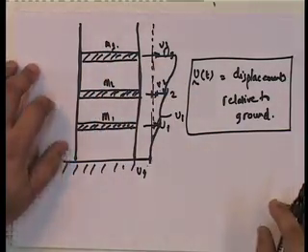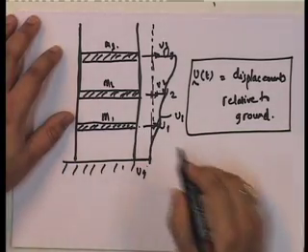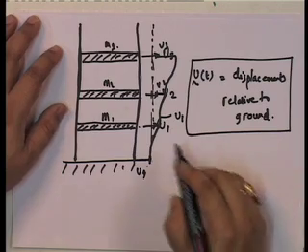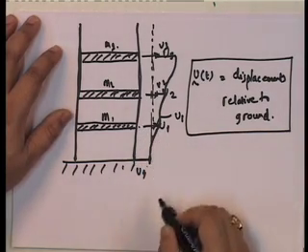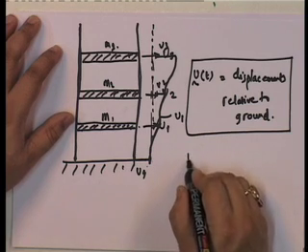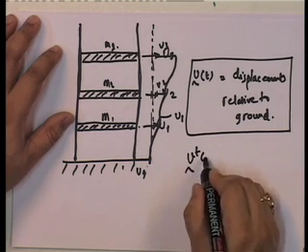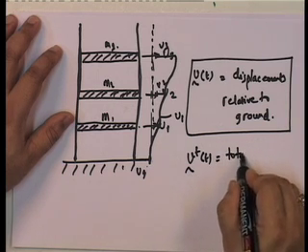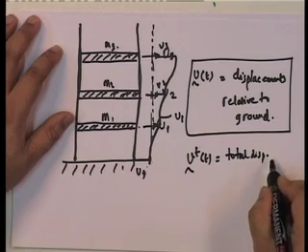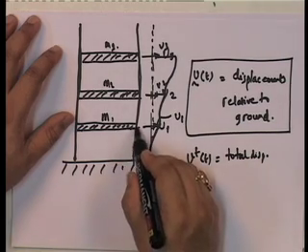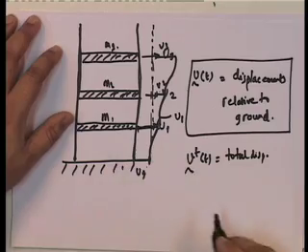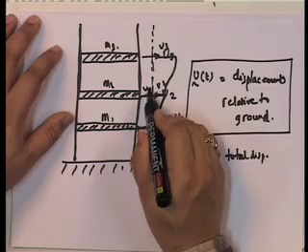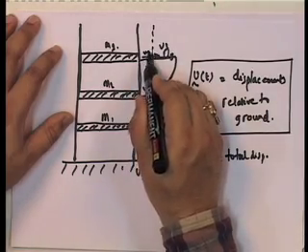So if you look at the inertial force, what we have is, if you look at this particular thing, you also have a V total of t. V total is the total displacement at the point. So this is the total displacement from here to here. That is called V total 1, this is V total 2, this is V total 3.